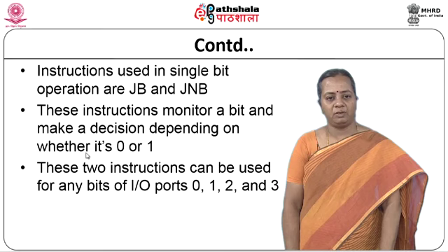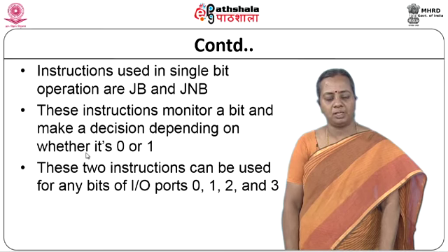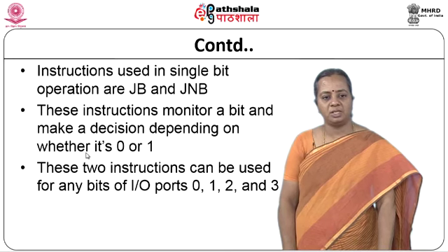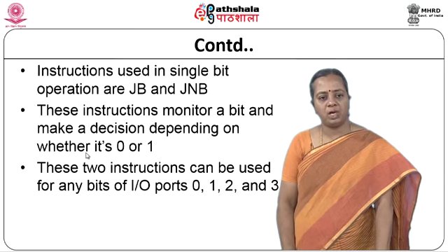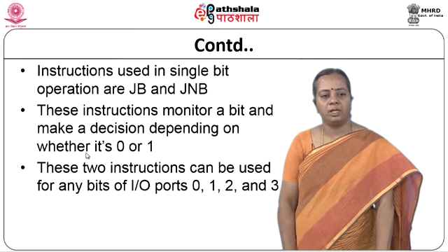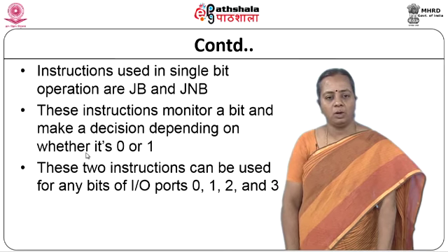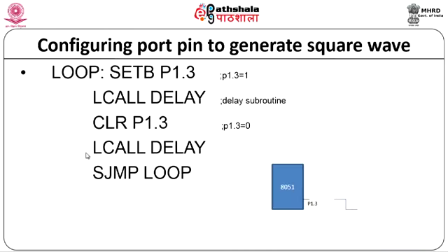Now we have gone through single bit operations as well as how we access the ports. These instructions are used to monitor a single bit, and based on that we can decide what process to follow if it is equal to 0 or equal to 1. Now see this example: with these ports and pins we can develop applications through the 8051 microcontroller.